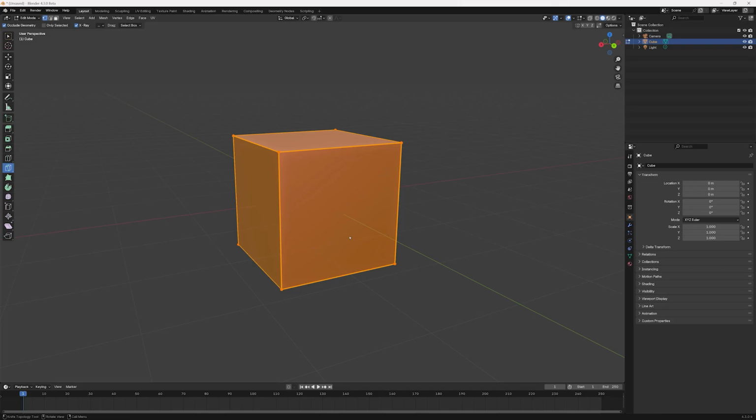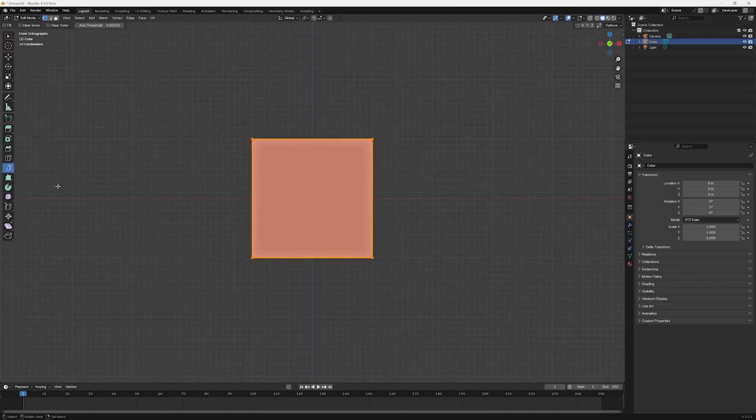The Bisect tool is the second option listed along with the knife tool. Unlike the other cutting tools we've looked at so far, the Bisect tool is capable of automatically cutting a mesh into two separate parts. When using this tool, it is often best to work from a named viewpoint position such as front. The first step is to select those faces we wish to cut through.